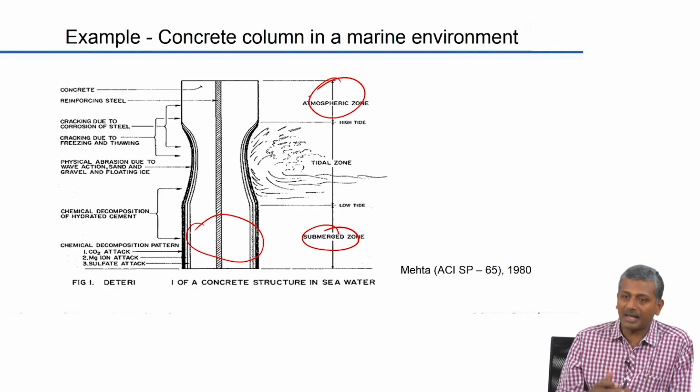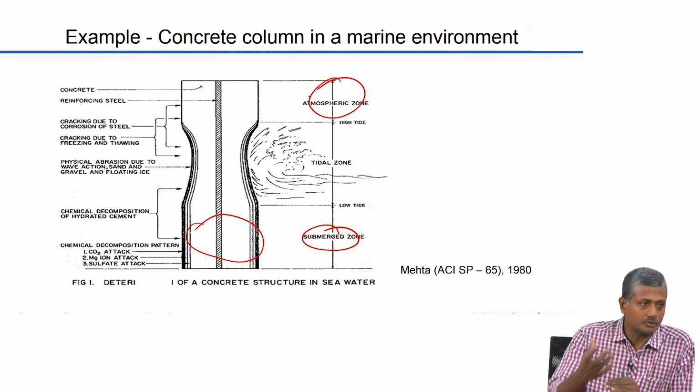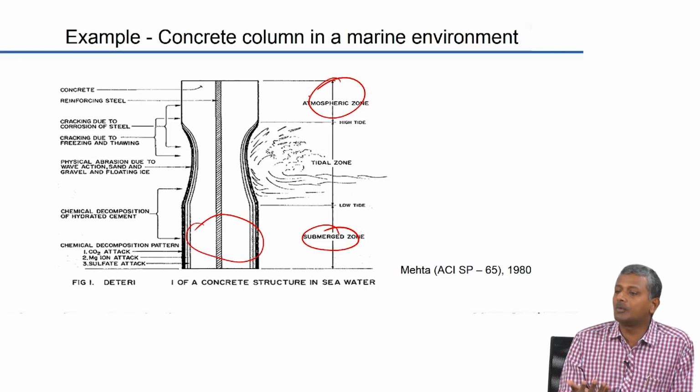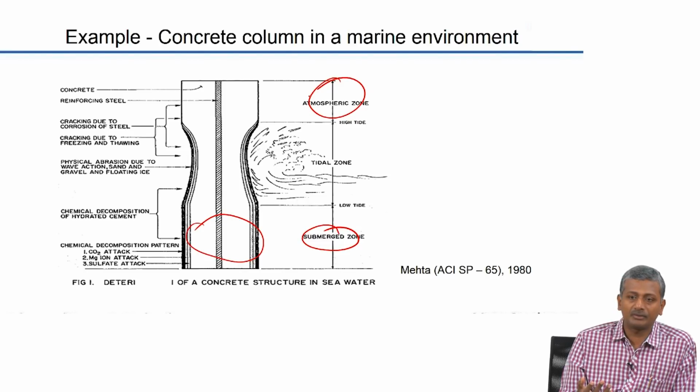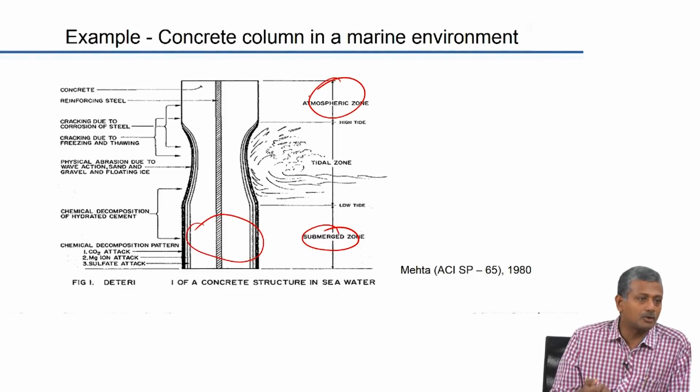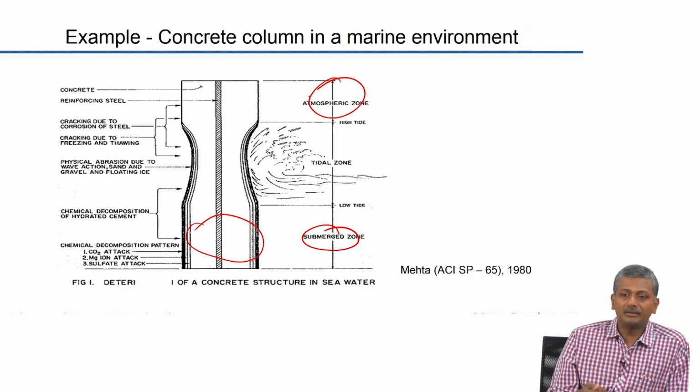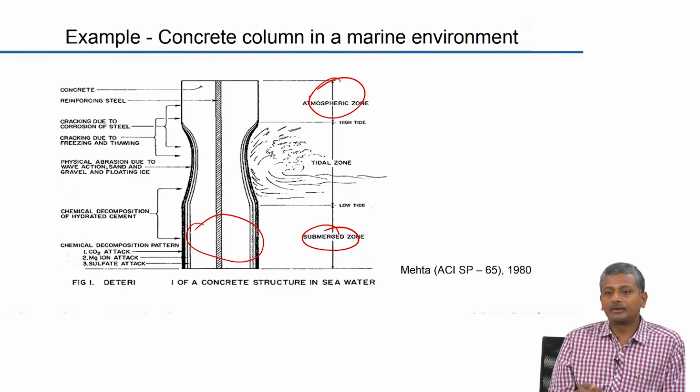Okay. So, it is not directly in touch with the water, but there will be salt spray. So, there will be drying and wetting. So, what sort of mechanism will act there? Sorption, there will be sorption, definitely sorption will be there. What else will happen? There will be Wick action because there is extreme drying happening on top, right, and to some extent there will also be diffusion.